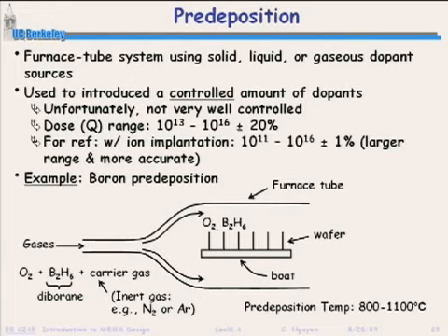It's just a dose. First of all, did I say per cubic centimeter? It should not be per cubic. This is per square centimeter dose. It's per area is what this is. So these numbers you can't compare with dopant concentrations in silicon, right?